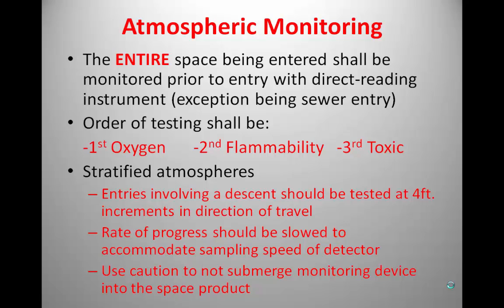One thing we can do to assist with this is tape a block, like a small piece of wood, on the end of the sampling probe, and that way if it does hit bottom, the piece of wood hits first and not that wand. There's a couple filters in the wand, and hopefully they will stop the travel of any product through the tubing to the monitor, but we don't want to take any chances with that and damage the monitor.